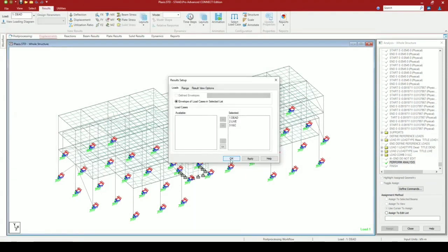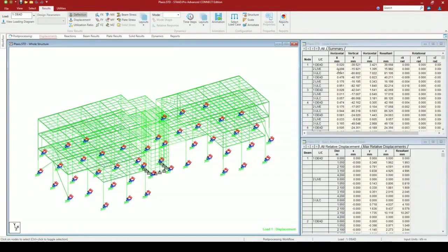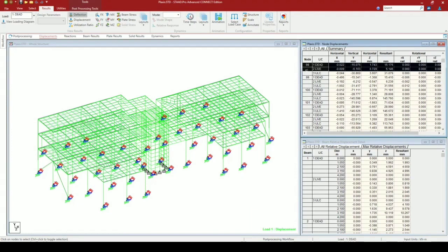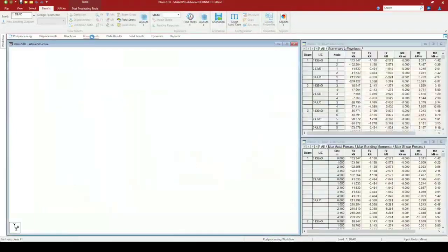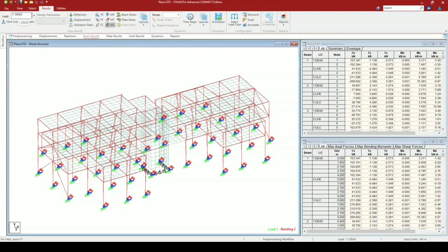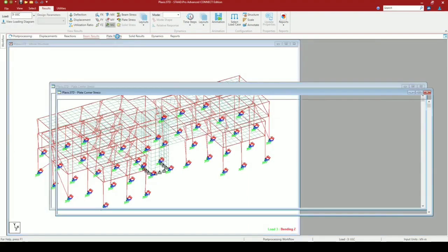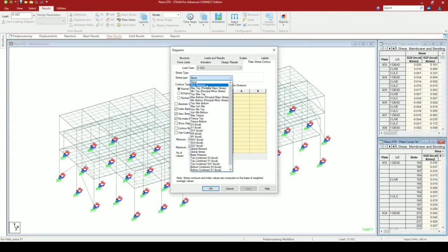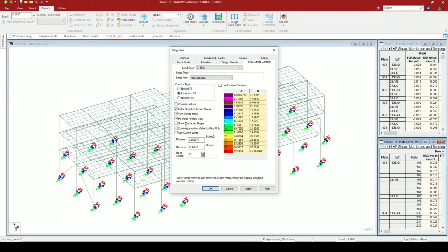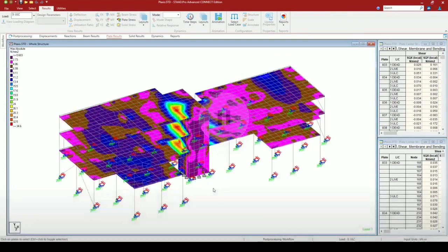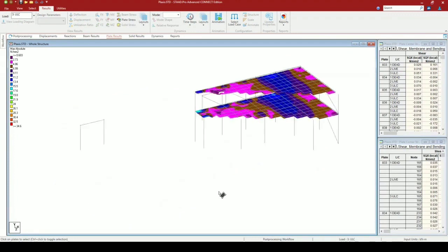And here, by going to the post-processing, I'm now getting my results for the individual nodes, the behavior of those nodes, how far they've deformed, utilizing the spring definitions for each of the primary load cases. One of the other things we could have done, but haven't in this instance, is define the supports to be compression only. Clearly, if we're looking at a structure where part of the model may rotate and the structure pulls out of the ground, we would need to consider that that is a one-way support, and we can have it as compression only. And here, just simply showing the difference in results resulting from that change in our support conditions.